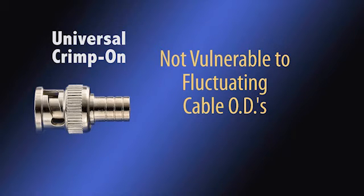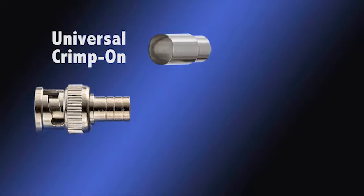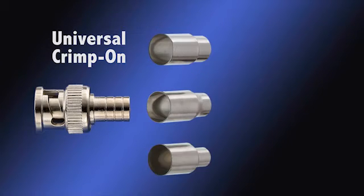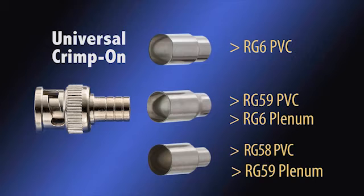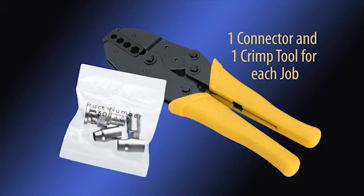This product is perfect for the service call environment, as it is one connector with 3 ferrules in the bag that will terminate the following cables: RG58 PVC, RG59 PVC and plenum, and RG6 PVC and plenum. Thus you have one connector for every job that you go on and one crimp tool that will crimp all 3 crimp ferrules.